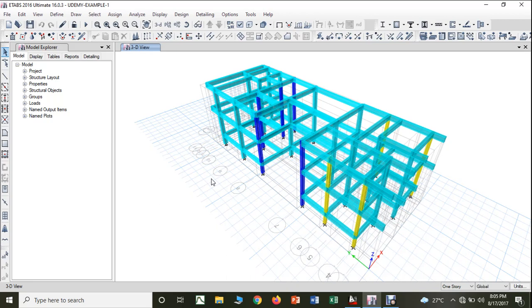In the same manner, on the beams which receive high loads, if you put a very small beam dimension, then definitely the beam is going to fail. So by keeping both things in mind, we have to understand where a particular beam has to be decided. Now, before we go on to the roof beams, first we will discuss the plinth beam.